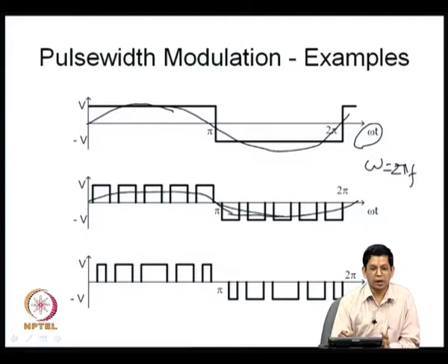Now, this is pulse width modulated. So, you have zeros also applied, and this is a little lower. By varying the widths of these pulses, you can vary the AC voltage that is available. This is one way. So, we are just trying to get better. It is possible for you to control the AC side voltage available. You can actually do better, as shown in this waveform. In this last waveform, you see that there are also 5 pulses, but their widths are different. The width is broadest at the center and the pulses are narrowest towards the end, which is roughly sinusoidal in fashion, the widths themselves.